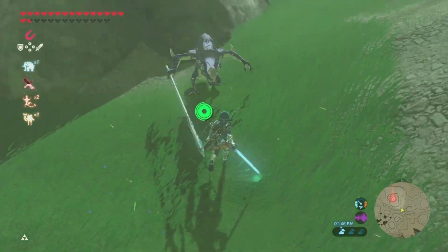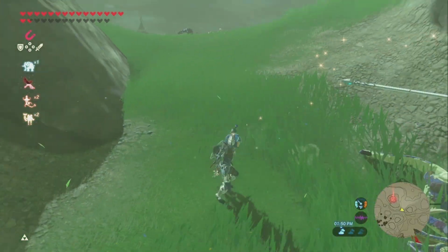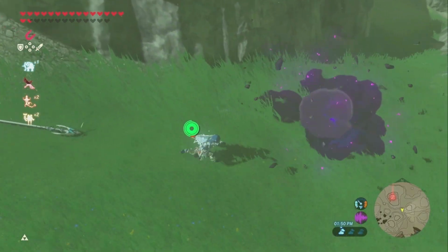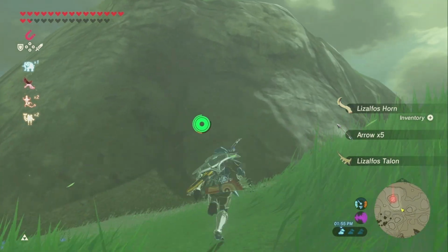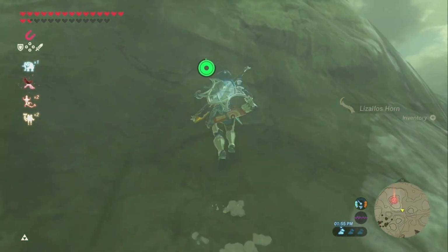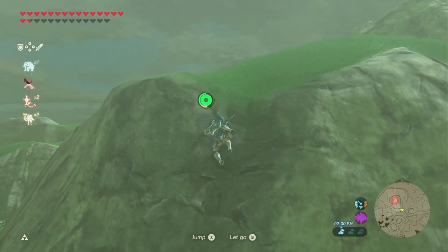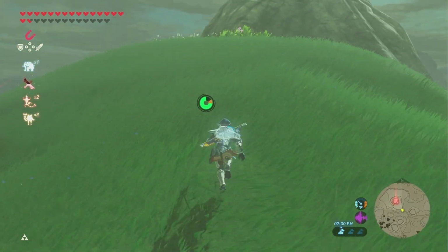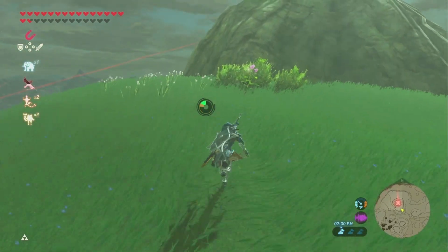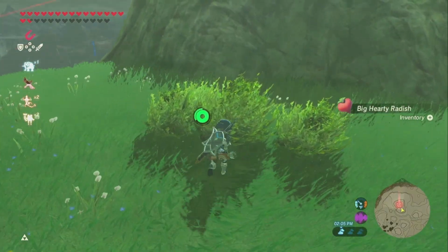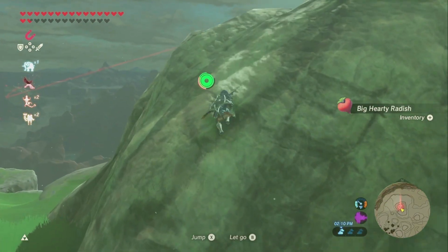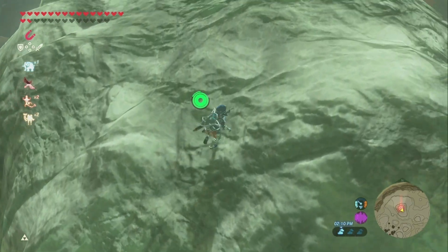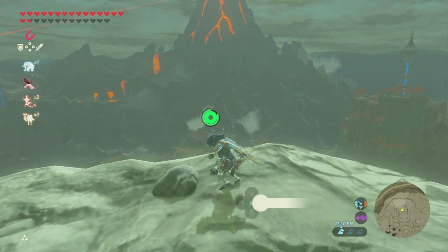The tank has supply and return pipes that go to a coil inside a duct system and/or to a radiant piping distribution system. When the house thermostat calls for heat, a pump moves water from the domestic water heater tank into the coil, and in a ducted system, air is blown over the hot coil.